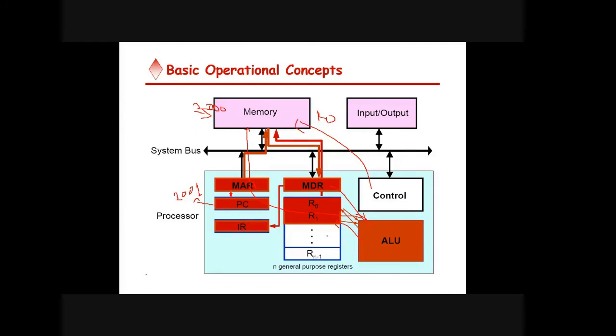When the instruction has all the operands in the general purpose register, there is direct execution by ALU. If any of the operands is not there in the general purpose register but is there in the memory, again that data address will be kept in MAR, a read signal will be generated, the data fetched to MDR and transferred to the general purpose register, and ALU will again execute the instruction, and the result will be stored into the general purpose register. This is the complete operation.